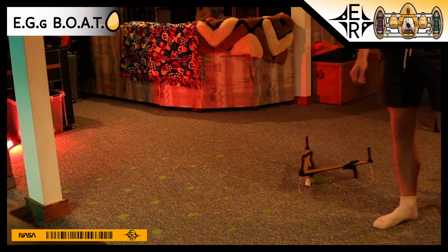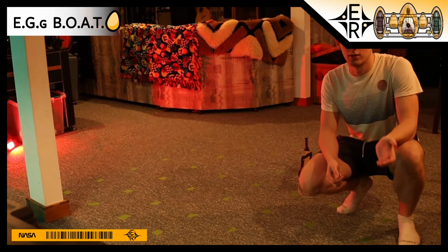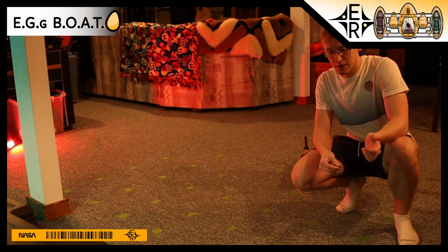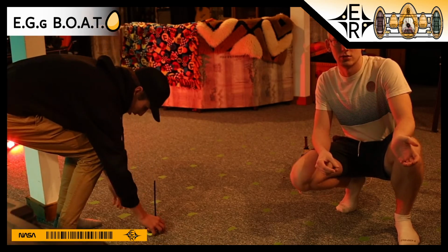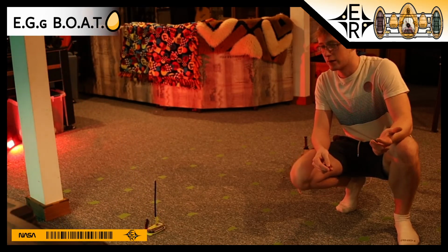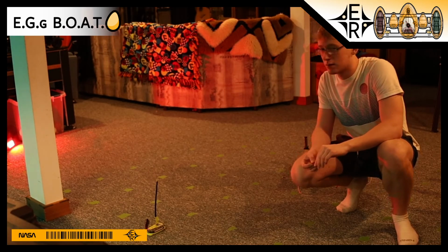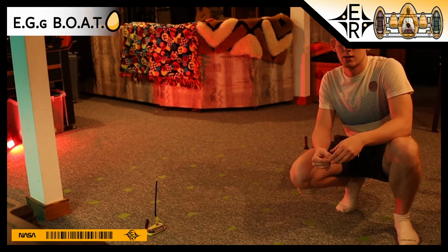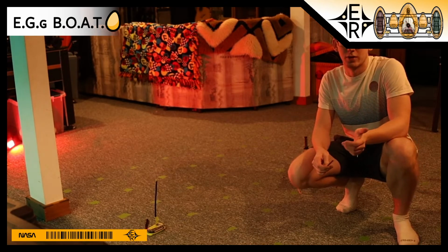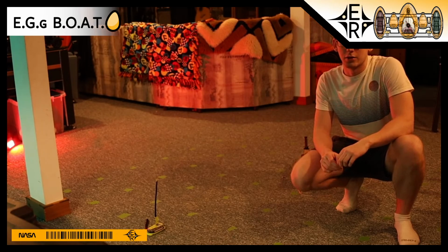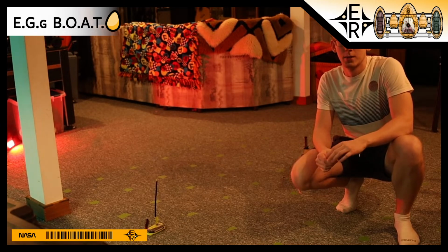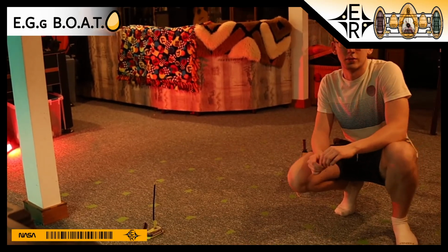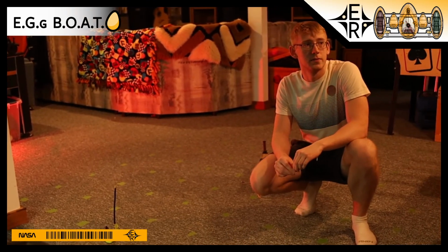So we'll be able to set the beacon in each spot, read out the 4 different measurements we get for the phase differences, and then create a database of those that we can use to compare values later. So if we can get an array of all the values that we'll read at different positions, then when in the field, when it reads a certain value, it'll compare it to that array, find the closest match, probably through some sort of least squares method, and then determine its location from that and navigate towards it.